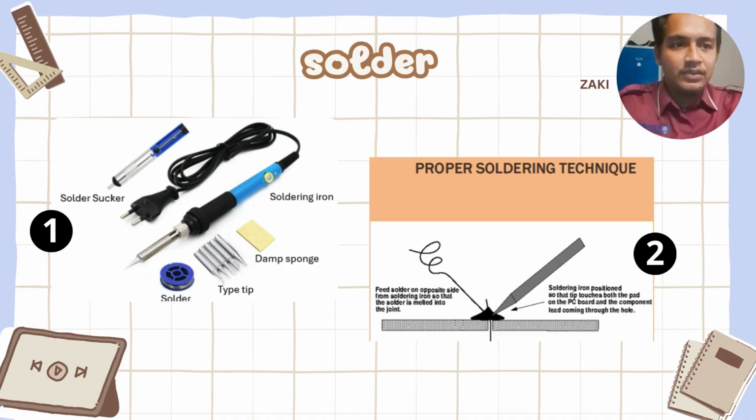For the soldering section, in figure 1, the solder tools, we use the soldering iron, damp sponge, tack tip, solder wire, and solder stand. For figure 2, the proper soldering technique involves the tip touching the pad on the PCB board and the component lead, and the solder wire on the opposite side so that the solder will melt into the joint.